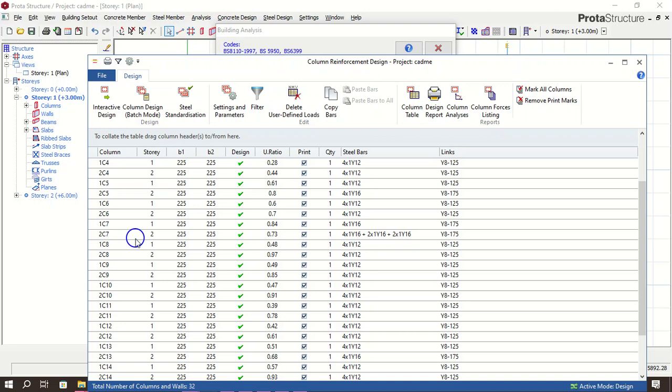there are three things that come into mind. Columns that are just axially loaded, there are no moments on those columns. Columns that are both axially loaded and subjected to bending in one direction, that is uniaxial bending. Then columns that are also subjected to axial load with bending in both directions, that's biaxial bending. So in a situation where you're designing the ground floor columns where there is axial load and there is moment, when you're working with the column interaction diagram, you see a lot of those things cancel out and you end up having minimum reinforcement.